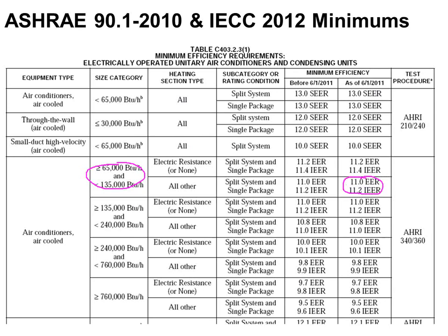Now, let me just point out one thing here. Every once in a while, somebody will send me a table like this from the code book and say, no, Ryan, you said it had to be 11 and 11.2, but the code really says it's 11.4 and 11 point whatever. When that happens, it's because you're looking at the wrong table in the book. Sounds a little crude, but that's what you're doing. There's a table way in the back of the book for additional efficiency options, and it looks very similar to this table, but it's only if you are in that bucket.